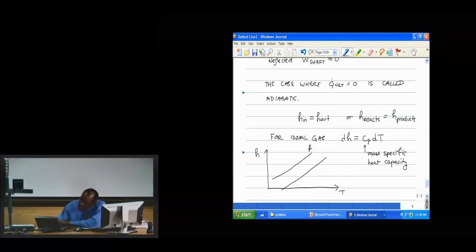So if we're at, say, 25 degrees C, some reference condition, we're going into this pipe with reactants at 25 degrees C. It's adiabatic, so we're in this isenthalpic system where H in is equal to H out. If I just go over until I touch the enthalpy of the products, the temperature that the products will be, and this is not to scale obviously, so there's a scale break here, is what you would consider the adiabatic flame temperature.